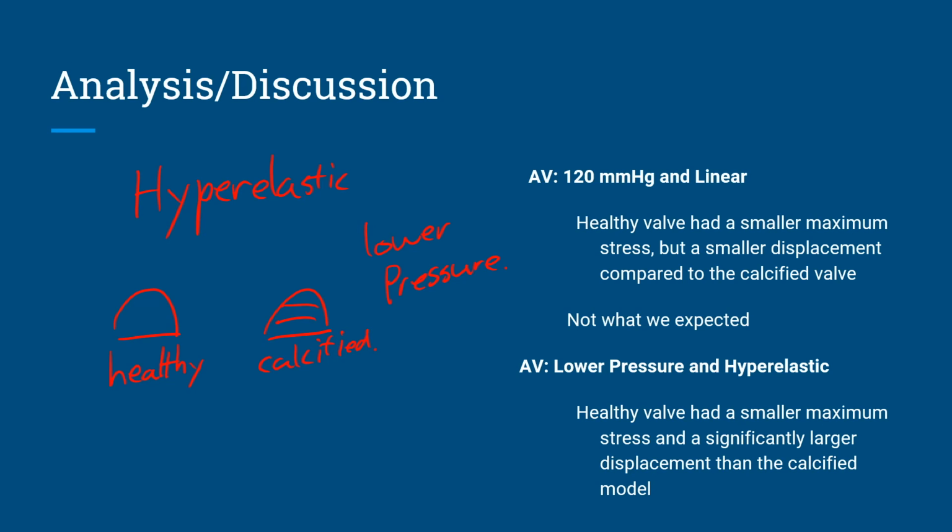However, we did try to make our COMSOL model a hyperelastic material under diastolic pressure, but when we tried to do this, the equations did not converge. We found this limitation in COMSOL after trying multiple things to get around it. So we decided to do one model that has the diastolic pressure and one that has the hyperelastic material properties. This way we were able to simplify the equations enough that COMSOL could calculate the stress and displacement for all our models.